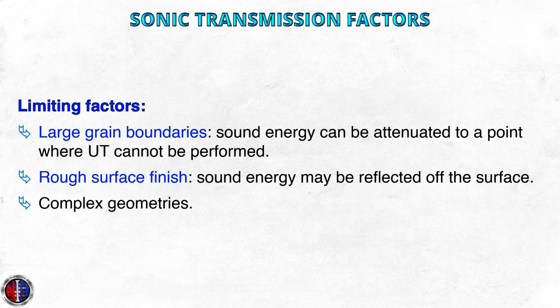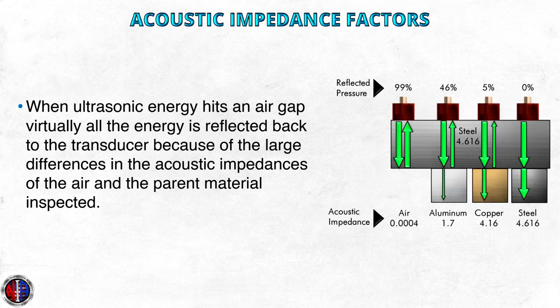Sonic transmission factors. Limiting factors. Large grain boundaries. Sound energy can be attenuated to a point where ultrasonic testing cannot be performed. Rough surface finish. Sound energy may be reflected off of the surface. Complex geometries.